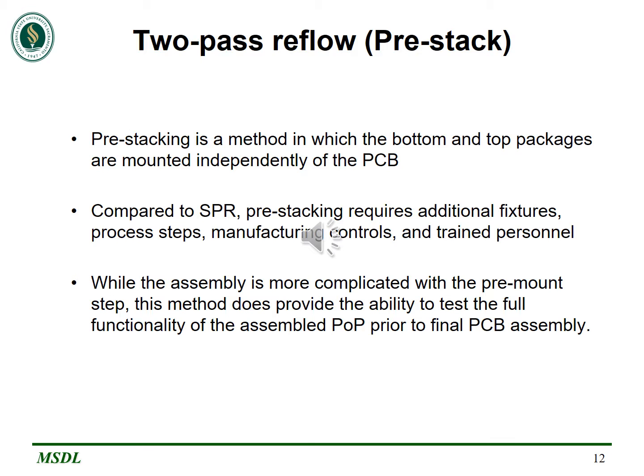Compared to the previous method, this method requires additional fixtures, process steps, manufacturing control and trained personnel. While this assembly is more complicated when compared to the first method, it allows us to perform a full functional test on the assembled package on package prior to the final PCB assembly.